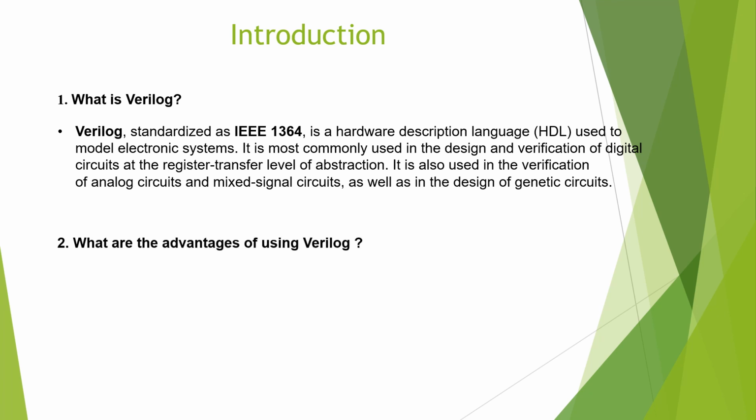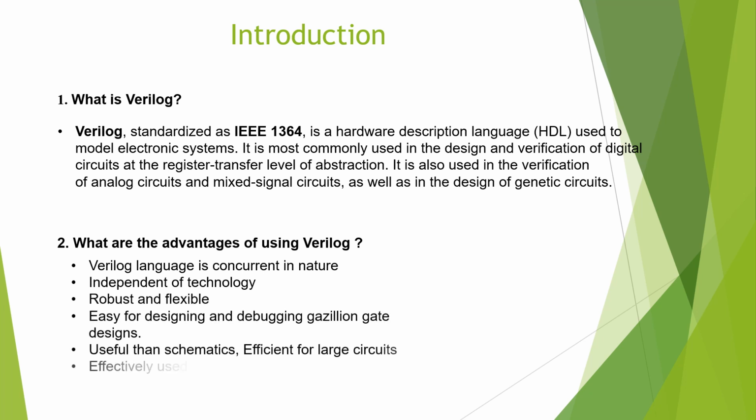What are the advantages of using Verilog? The Verilog language is concurrent in nature. That means you can have multiple events proceeding at the same time. It's independent of technology. It is robust and flexible, easy for designing and debugging gazillion gate designs. Gazillion in the sense the designs can be millions, billions of gates. It is much more useful than manual schematics, and it's very efficient when it comes to large circuits. It is used widely and effectively in the semiconductor industry, with extremely fast design and verification cycles.